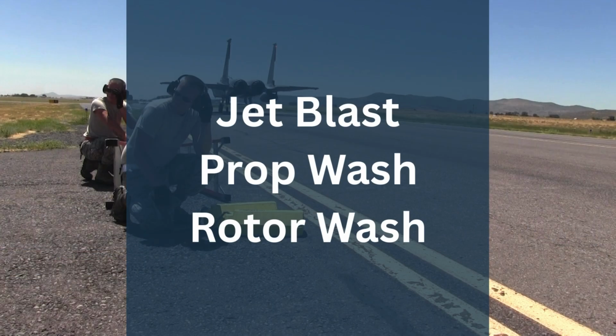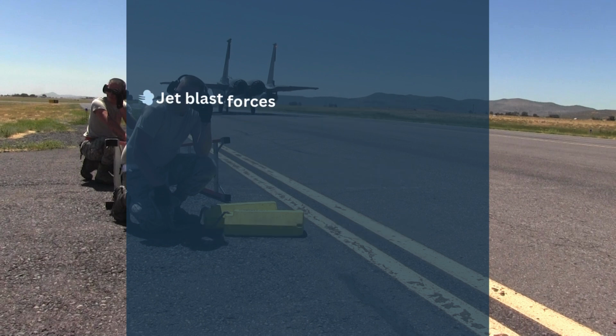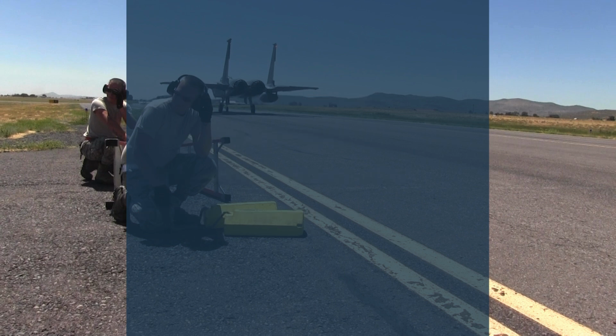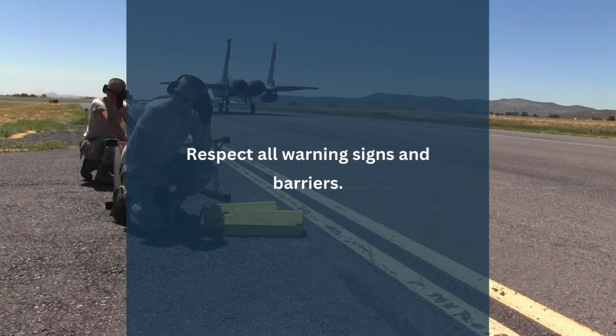Next, let's talk about jet blast, prop wash, and rotor wash. These forces can be intensely powerful, capable of knocking down people and equipment in seconds. Jet blast, in particular, can reach extremely high temperatures, adding the risk of burns and heat damage. That's why it's critical to stay outside designated safety zones and respect all warning signs and barriers.